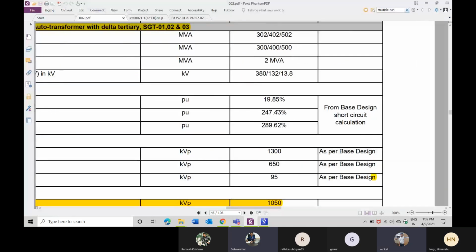That is extremely high because when they are trying to convert that to a 500 MVA base, it becomes high. If you want to test this with a delta winding, you cannot load the delta winding beyond its rating, correct? Whenever you are doing a short circuit test for a transformer with multiple windings, for 2 windings, the lowest winding rating is the limit up to which you can load it.